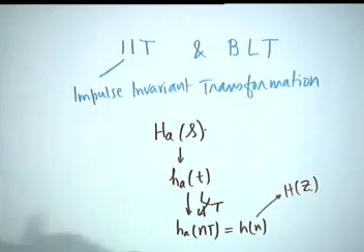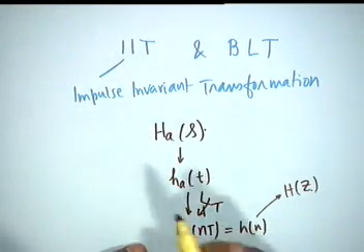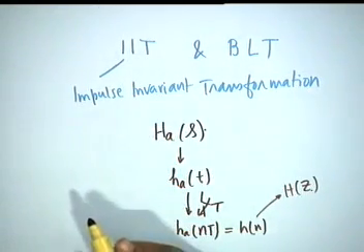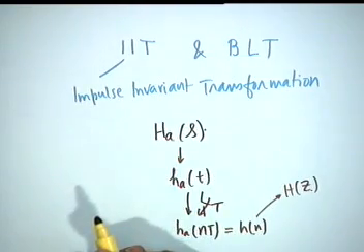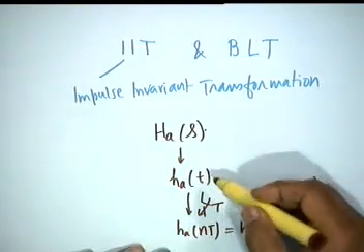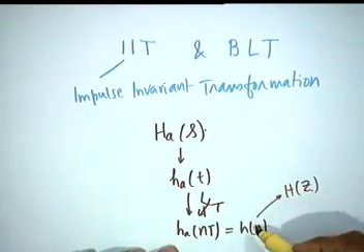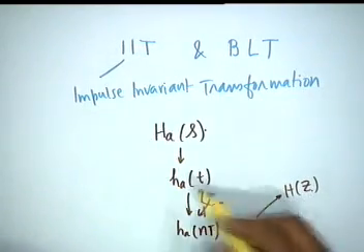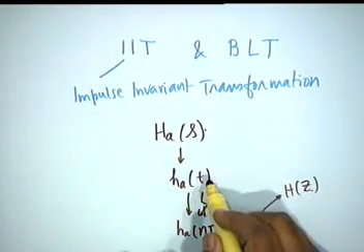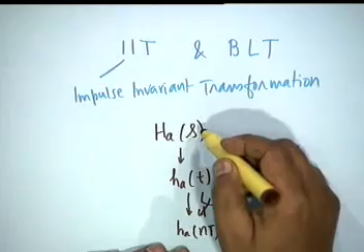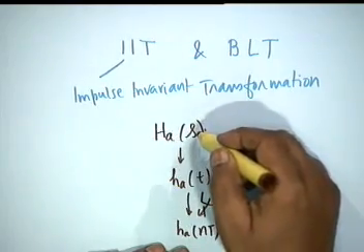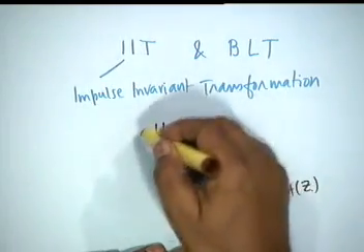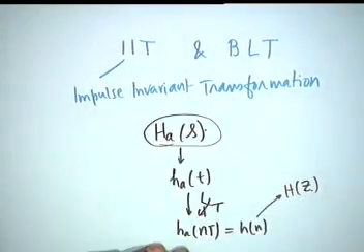This is why aliasing occurs, because no transfer function in practice is band limited. If you want to respect the sampling theorem, the sampling frequency must be greater than or equal to twice the highest frequency at which H A of s is non-zero.